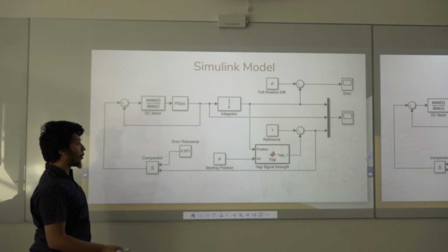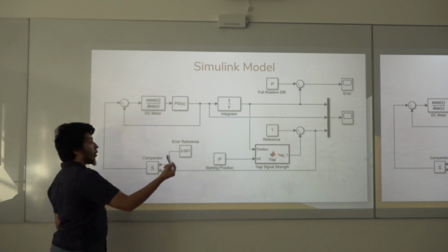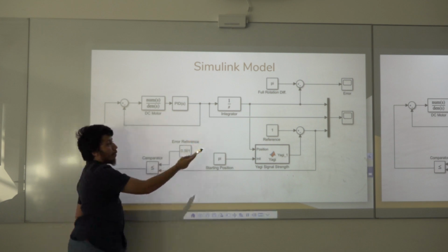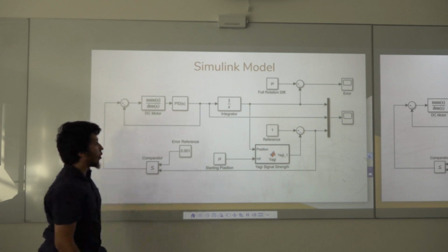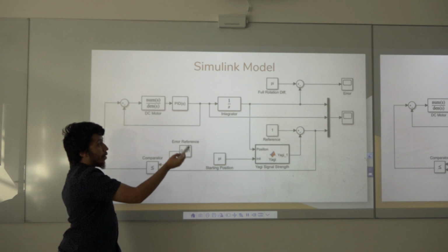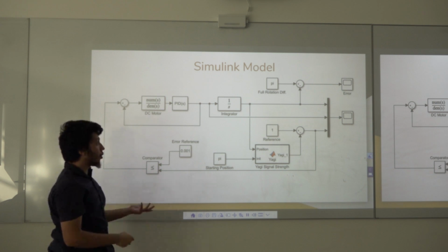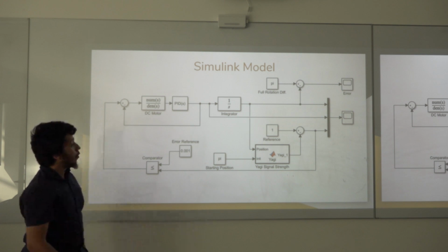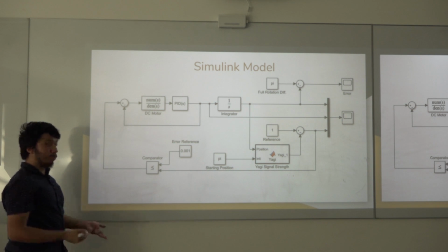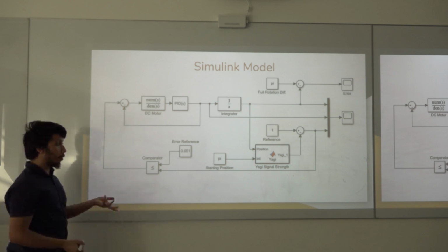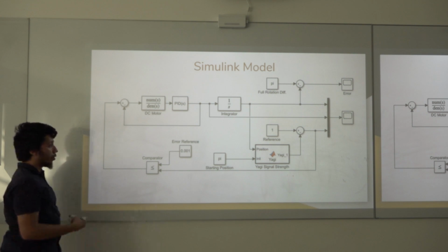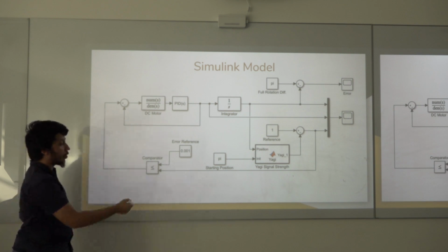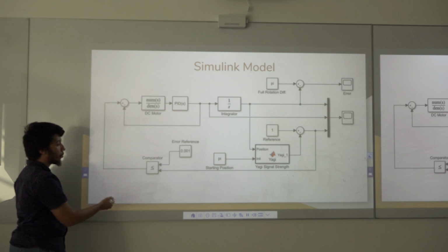For graphing purposes and for presentation purposes, I went ahead and selected the position of the motor to graph, the velocity of the motor to graph, and the compared signal strength to graph, as well as the error between our starting position, our current position, and the final necessary position to go towards our signal source. For the simulation, we assume that the signal comes from a 0 degree angle to make the calculation easier. Of course, if the system needed to be initialized in some other direction, we only need to change the starting positions and the extra positions otherwise.